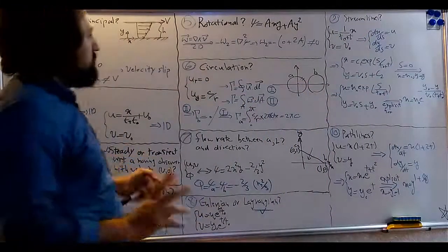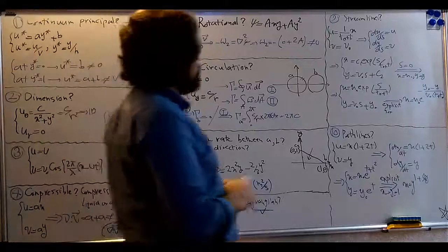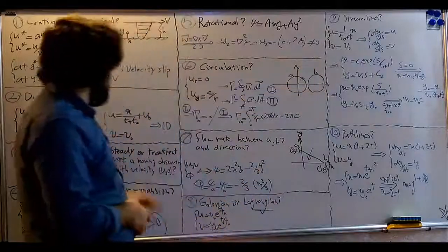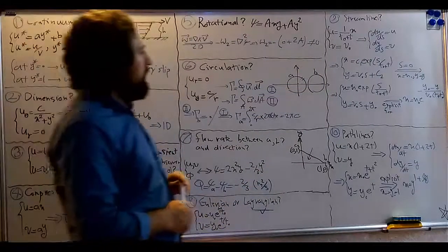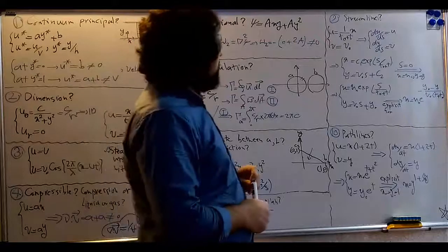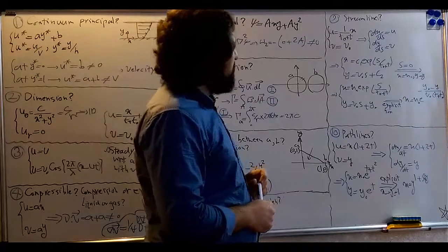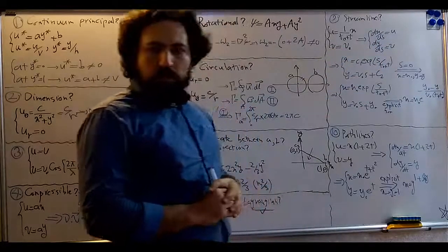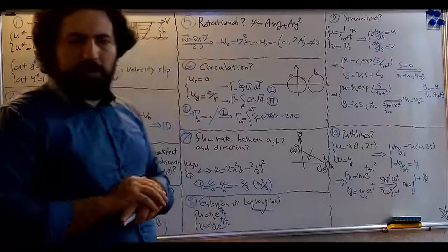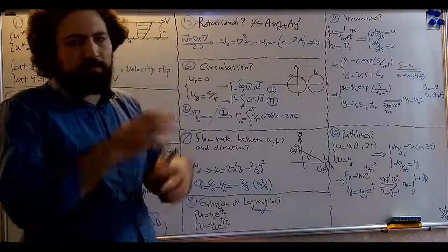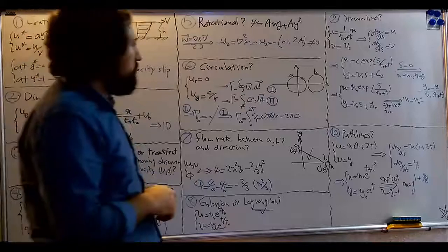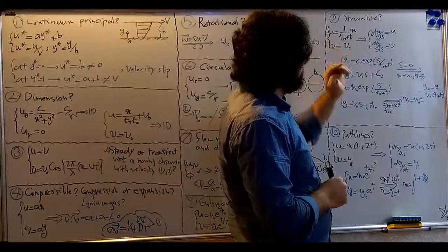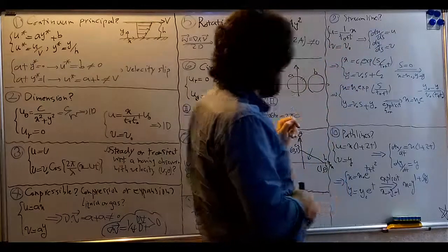Question number 9 is about streamlines for a one-dimensional velocity field. Exactly this case is given, a transient one, and you have to find streamlines. This is the formula. s is a coordinate attached to the streamline, and its origin is at x sub 0 and y sub 0, for example. And the derivative of x with respect to s equals u, and similarly for the other direction.